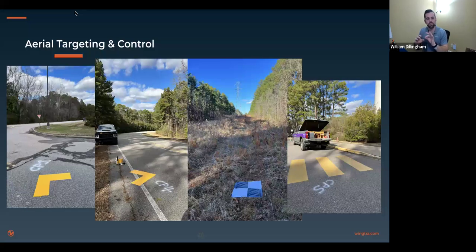That's all aligned to the inertial measurement unit inside, so all the individual laser channels are precision aligned with the inertial system. We do that in a dynamic application: we fly it, gather all these points, and then precision align everything.